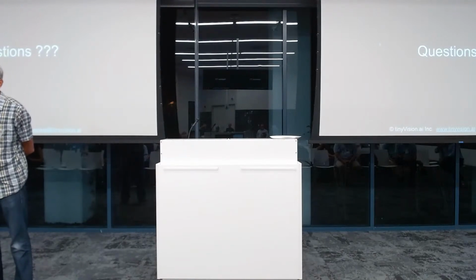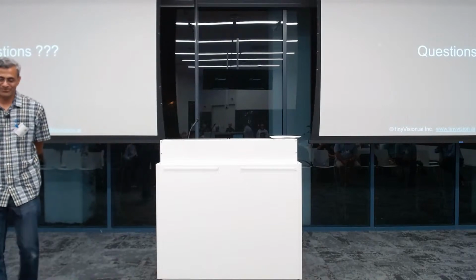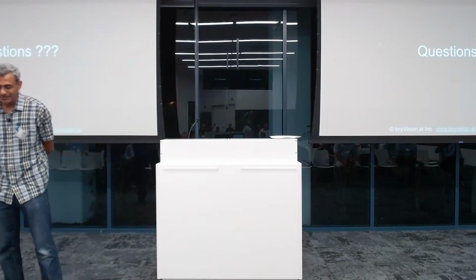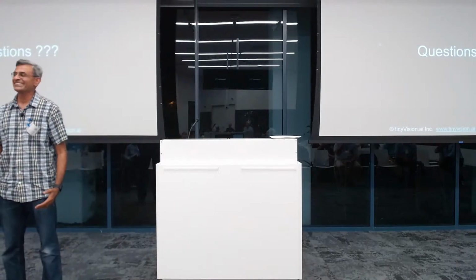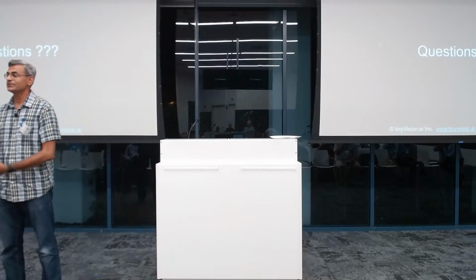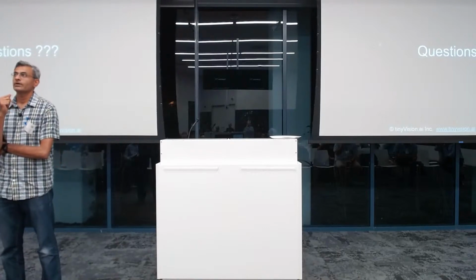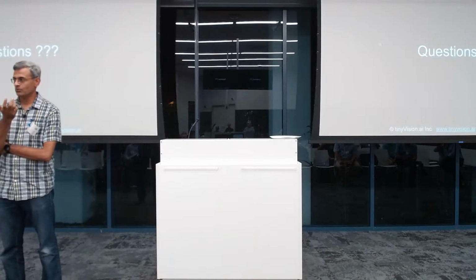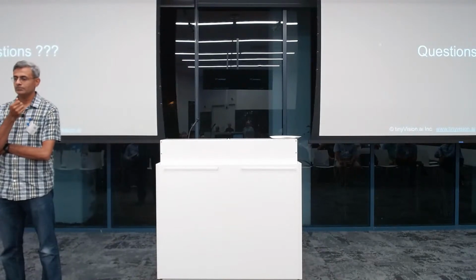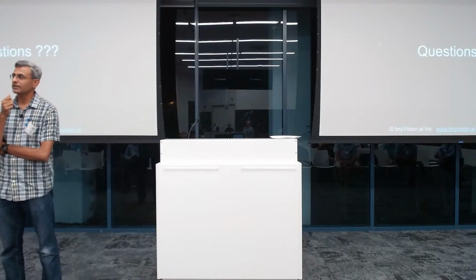And also, what about performance metrics, like TOPS per watt? Do you have any numbers for efficiency and comparison? I am certainly not anywhere near that number. Is it below one? Oh yes. So, to give you some idea, the imager is a QVGA, which is 320 by 240 monochrome global shutter, and running a VGG8 type network.